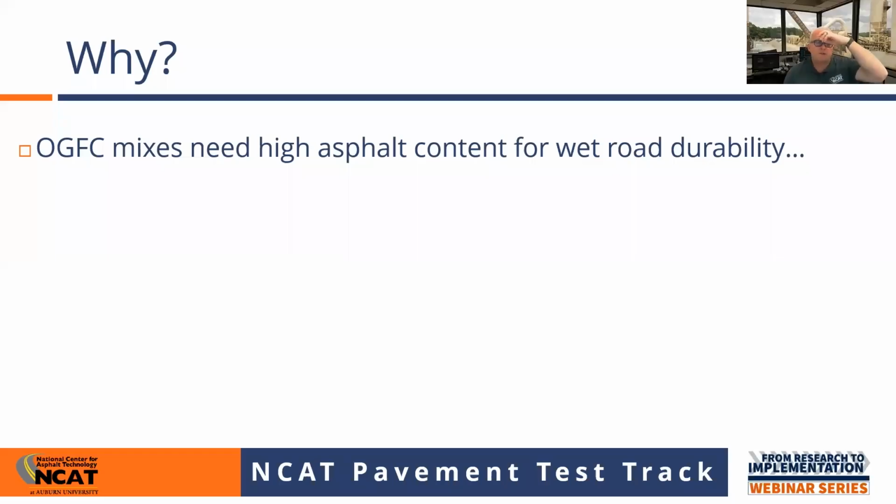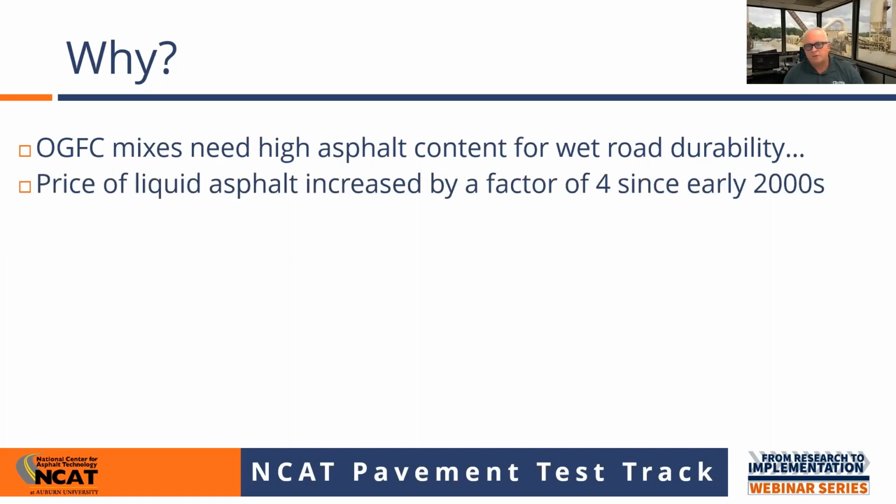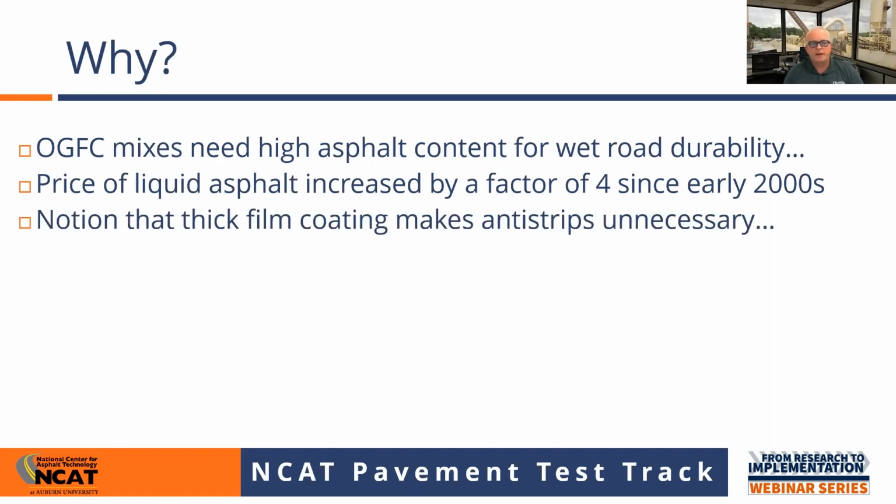And of course, OGFC mixes need a high asphalt content for wet road durability. But since we started doing this research in the early 2000s, the price of liquid asphalt has increased by approximately a factor of 4.